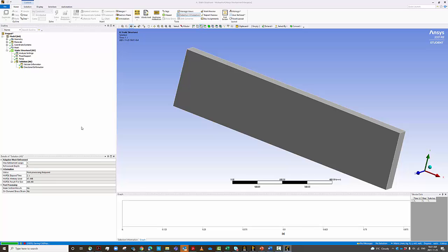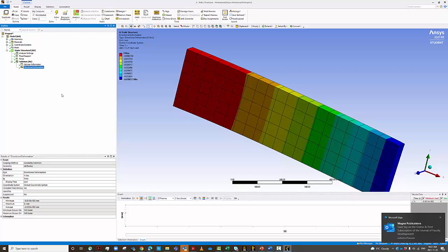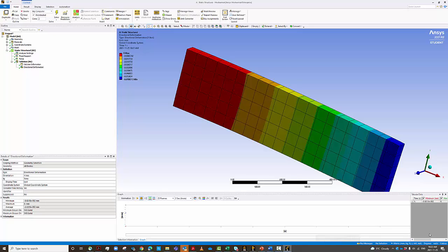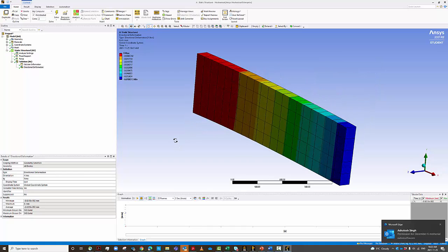So solving again should take longer time, but then I'll go to the direction, right? So you see here minus 0.00655792, right? Again, you can see here there is a change in the value, but how much is the change? You need to set a criteria for yourself. So you say if the change is less than 1%, then I'm going to stop it. If it is 10%, depends on what exactly you want to do. So the criteria depends on the solution and what exactly you are looking for. But 5% is a reasonable criteria, right? So at 105, this is the value. So you need to calculate the difference. You calculate delta in the deflection, and then you do it.